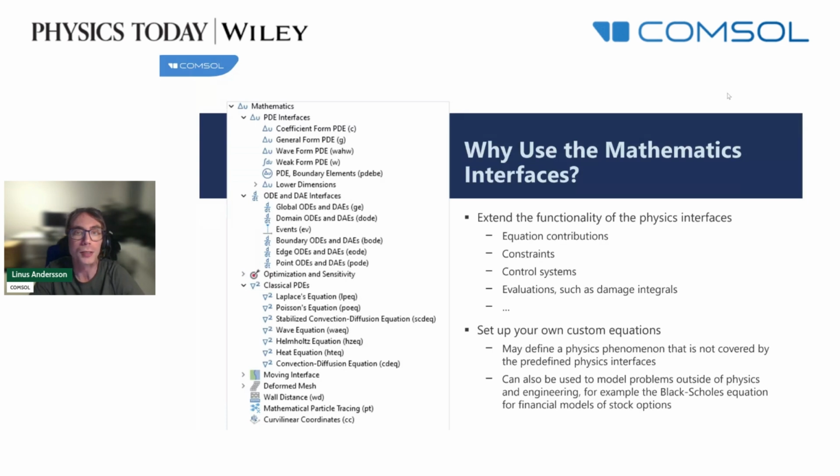Let's now first have a look at the tools that we have for equation-based modeling. On the left of this slide, you'll see a list of our mathematics interfaces. The most important ones are the PDE interfaces, partial differential equation interfaces. The ODE and DAE interfaces contain some subsets of the same functionality, and the classical PDEs are similar to the PDE interfaces, but with some commonly used equations already in place.